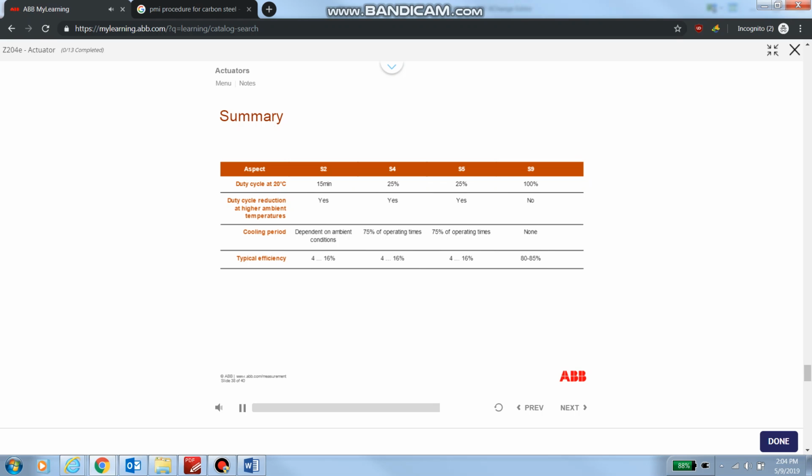In microprocessor controlled actuators of the S4 and S5 operating modes, the actuator usually increases its deadband automatically as soon as the permitted load is exceeded within 1 hour, or if the duty cycle has been overrun. The accuracy of the actuator is reduced as a result. The maximum dead zone is usually plus/minus 5%.